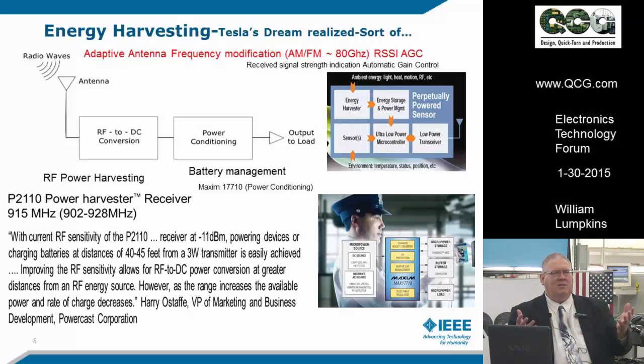So I imagine in the audience, people have cell phones. And my guess is your cell phones are turned on, not turned off. Hopefully they're in the silent or vibrate mode. But every one of your cell phones right now is emitting RF energy. What if we could harvest that RF energy? And how much RF energy are we talking about? Well, we're talking about Wi-Fi, and a Wi-Fi radio in a cell phone transmits normally at 15 dBm. You can recapture almost half a milliamp off of that 15 dBm, just from one cell phone.